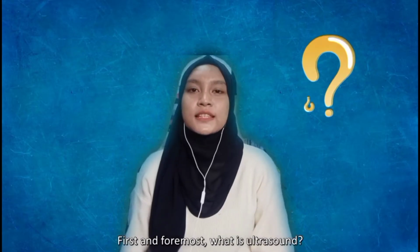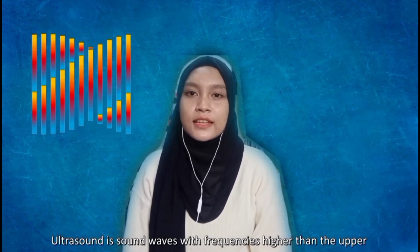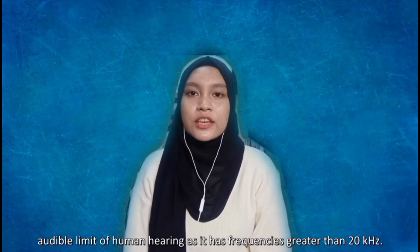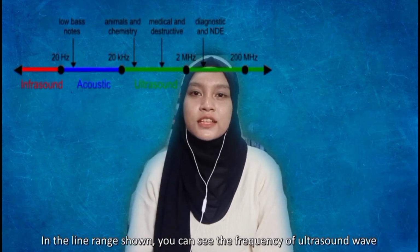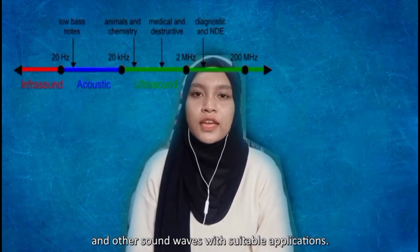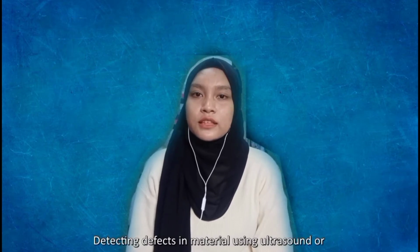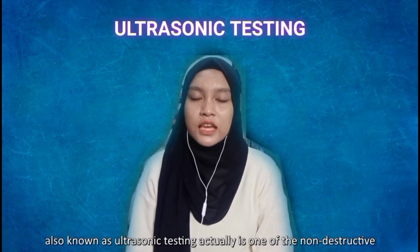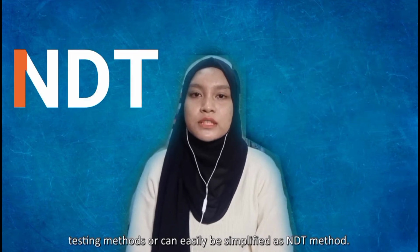First and foremost, what is ultrasound? Ultrasound is sound wave with frequencies higher than the upper audible limit of human hearing, as it has frequencies greater than 20 kHz. In the line range shown, you can see the frequency of ultrasound wave and other sound wave with suitable applications. Detecting defects in material using ultrasound, also known as ultrasonic testing, is one of the non-destructive testing methods, or simply NDT method.